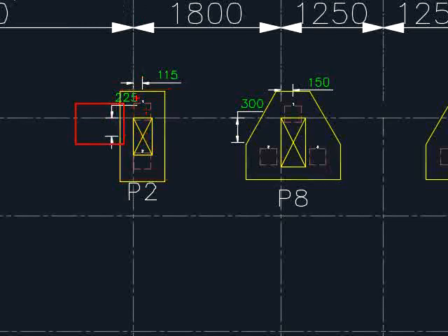This will lead to an offset distance from the grid line. You will need to clearly indicate the offset distance, and you can calculate it geometrically based on the dimensions of the foundations. These dimensions you can refer to in the course on reinforced concrete design too. There is a chapter regarding foundations.